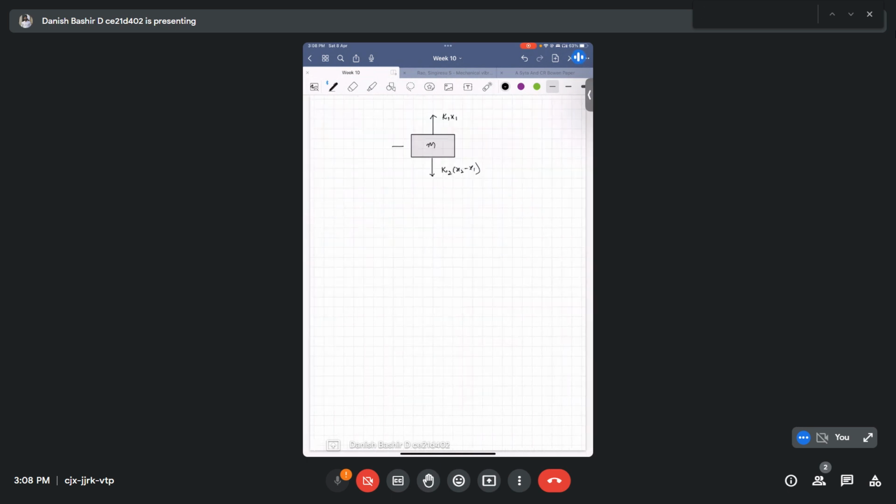Here we have x1 of t. And one more thing, in the opposite direction of the motion, we also have to give a fictitious load, which is proportional to the mass of the system and the acceleration of that point mass, m x1 double dot. Okay, this is the free body diagram of mass M1.